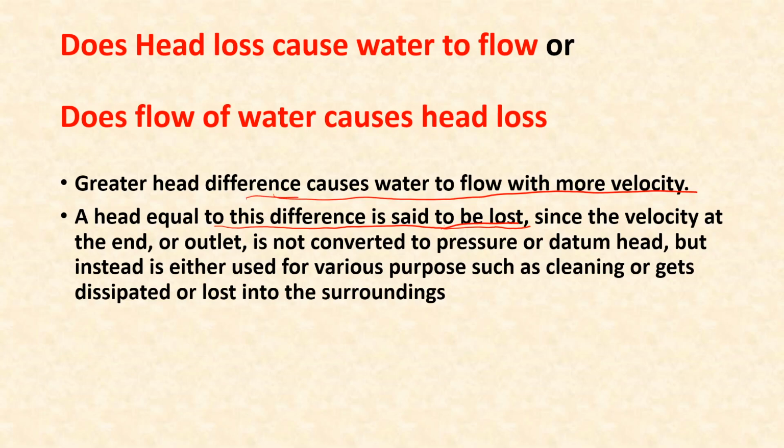Whatever was the head difference, it is converted to kinetic energy, and we are calling it to be lost only because that kinetic energy is generally not restored back or converted back into pressure or datum energy, but it's either used for various purposes such as washing or cleaning and so on, or if you keep the tap open without using the water, then it is just lost into the surroundings. That's why we say that it is the loss of head.